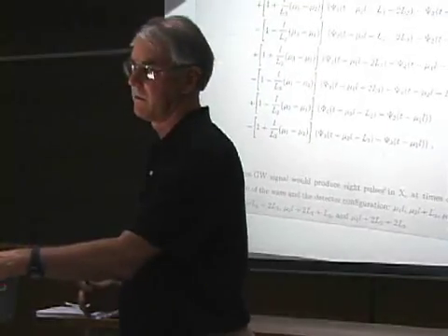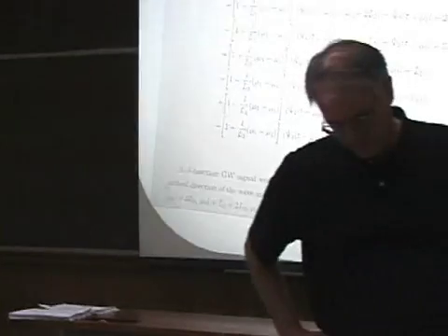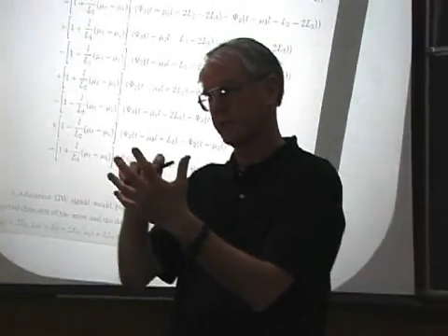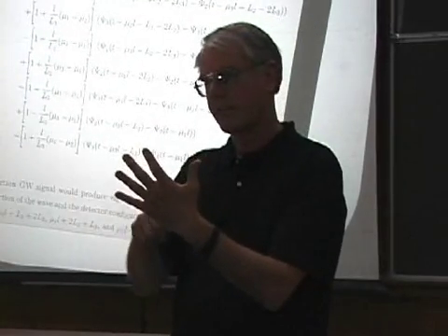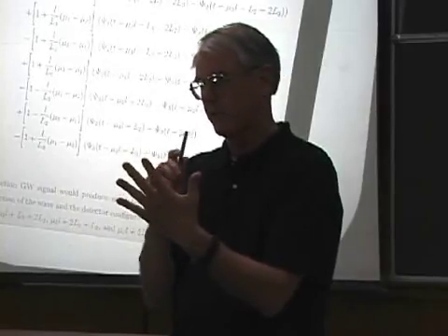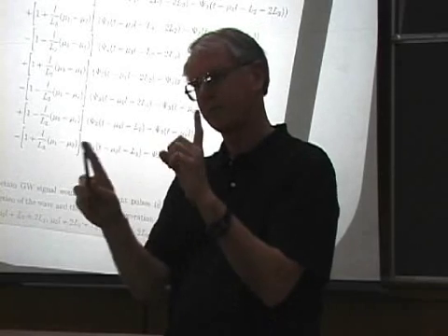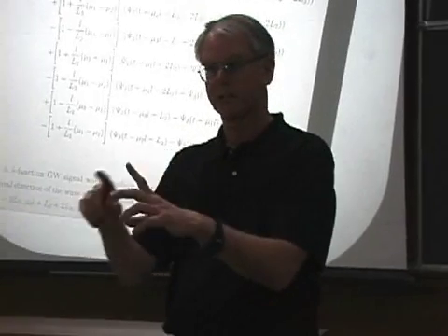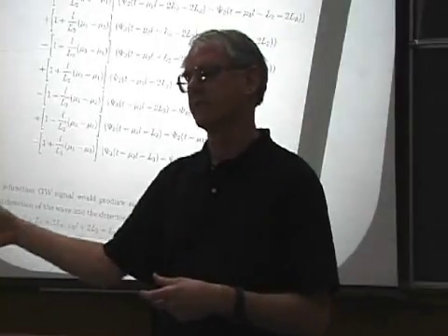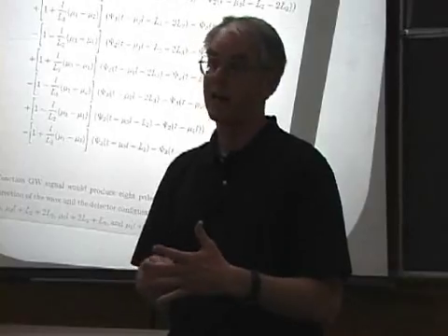Yeah. Now, what about when your timing data is going to come at kind of 1 second weeks or something? So those delays will fall between. Right. Okay. I'll blather on. I haven't thought about this carefully, but it seems to me that what happens is that you have synchronized clocks on these things, and you're sampling pretty darn fast. Yeah, 10 megahertz is not bad. The sampling is going to be a problem. I think that's one of the practical problems I want to talk about at the end. But for the moment, putting that aside, you just have to keep track of these pointers about which sample you really want. You're going to take 10 million samples per second, but you're only going to pass a few of them over the telemetry link to actually be used. So you have to have the clock synchronized, but you have to do that anyway for other reasons, I think. But that's how I would do it if I were tasked with the problem.